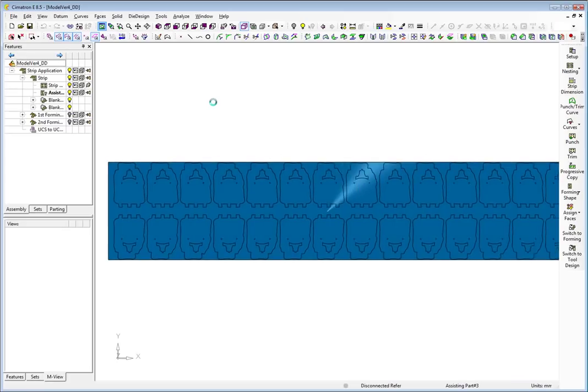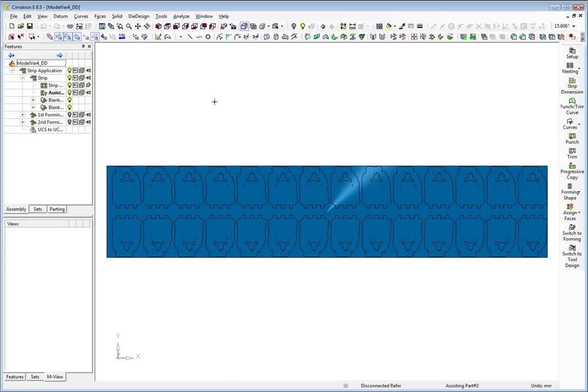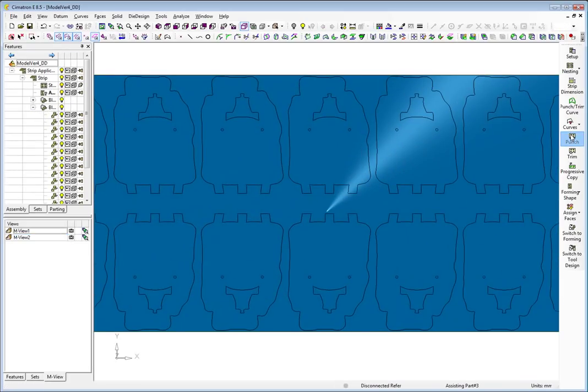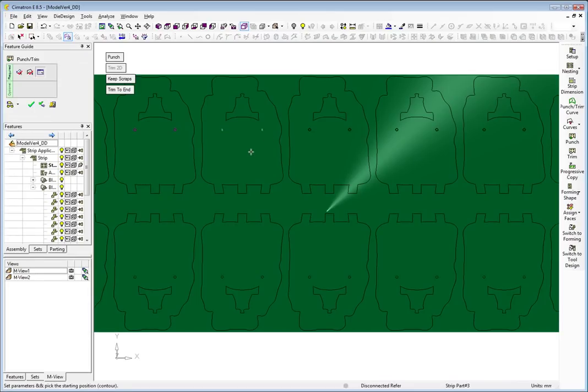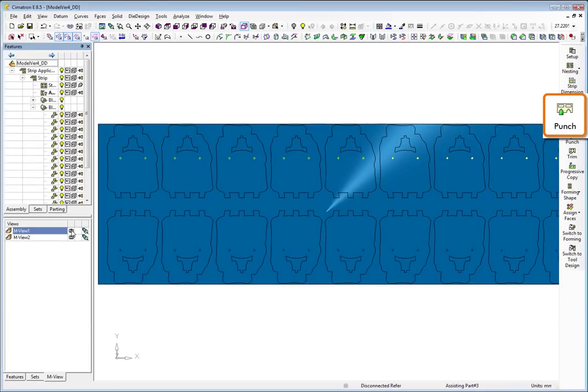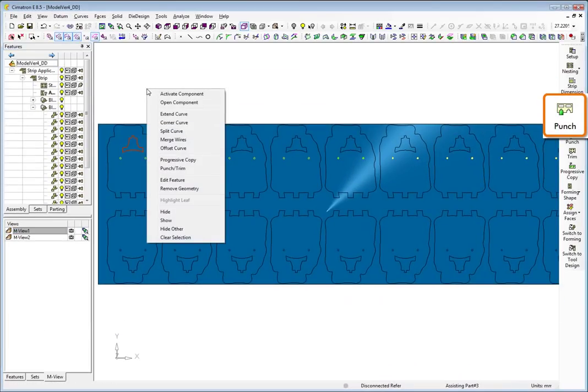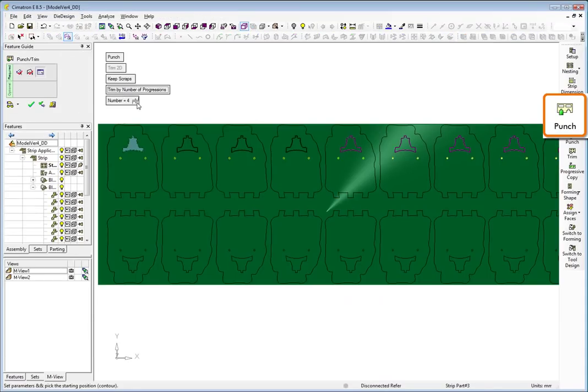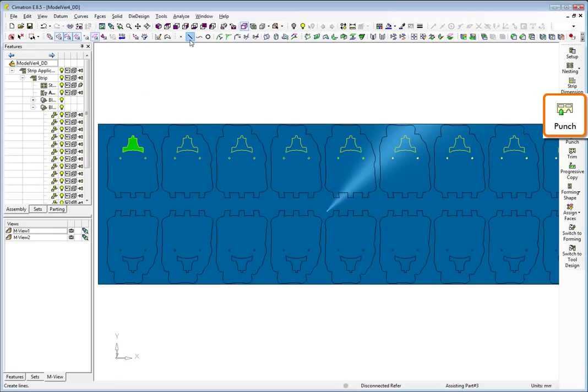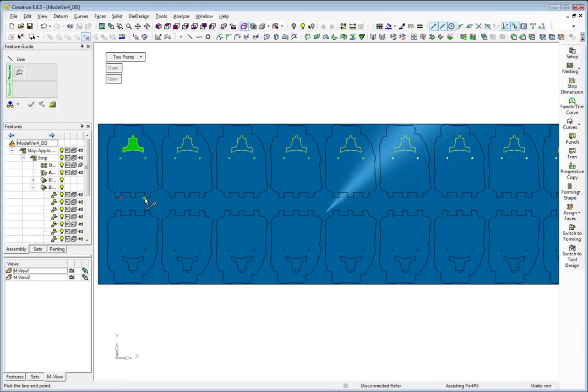We will now create the internal and external trimming punches. Creating punches is incredibly fast. Simply point and select the location of the punch and the system will do all the rest for you. Note that Cimatron enables you to enjoy all the benefits and speed of working in 2D mode. Your output is actually created in the background in 3D.